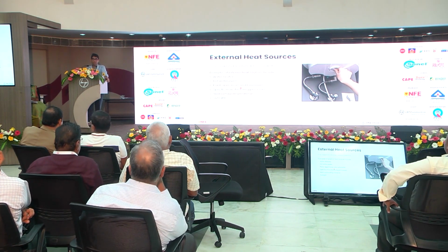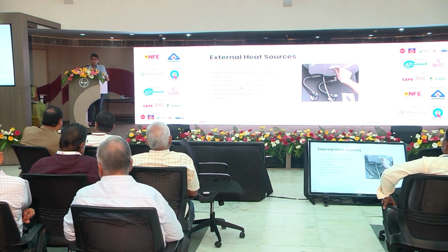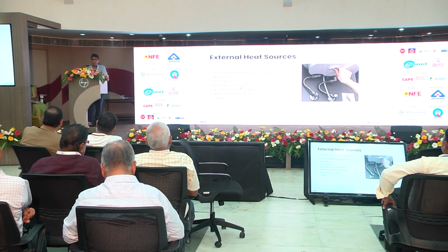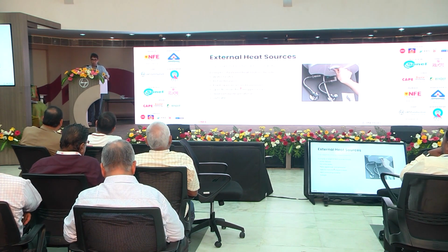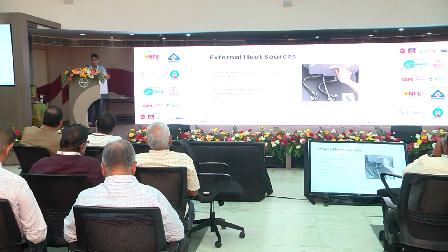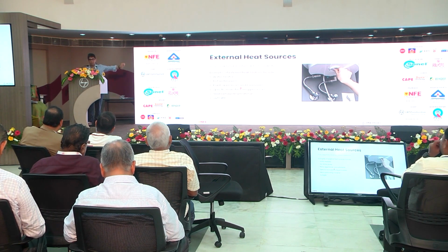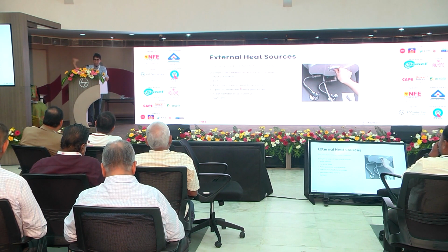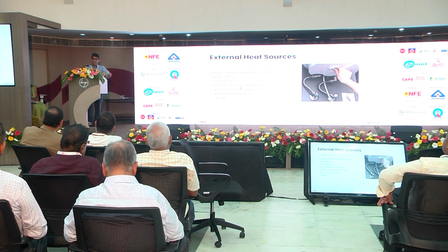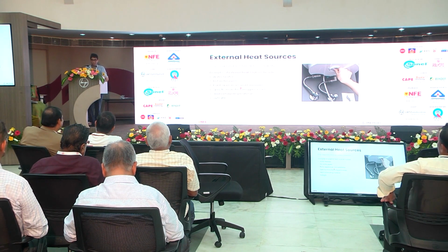In fact, I was involved in a project once where a bathroom was being renovated, and they had to waterproof the floor, but it was the monsoon. So the contractor said, can you put a halogen light here to help heat it up? So some electrician came and put a halogen light. Later on, when I went on site, a circuit breaker had tripped. When I went in, I saw the halogen light melted the cables. So you need to think about all these things.